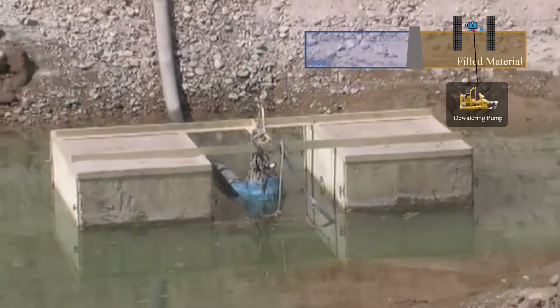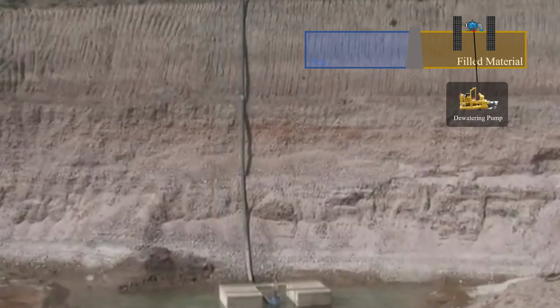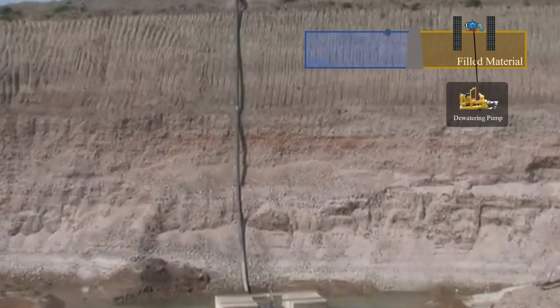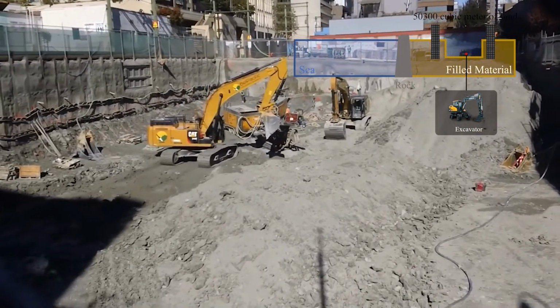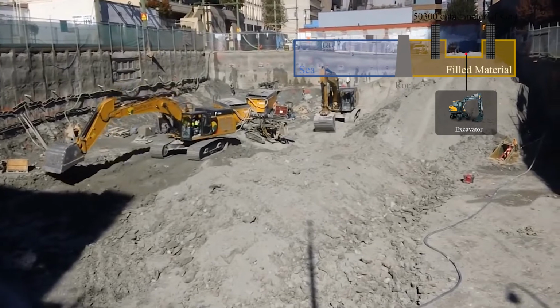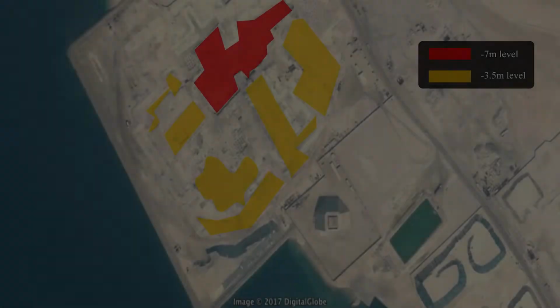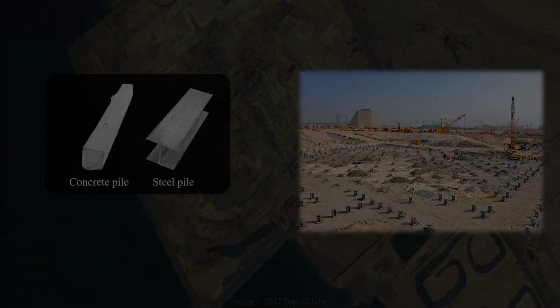On the ground surrounded by the bars, a pump was used to drain water 7 meters below sea level. 50,300 cubic meters of sand were excavated while the water barrier was built and the ground was drained. The land was excavated differently at 7 meters and 3.5 meters depending on the location of the building.